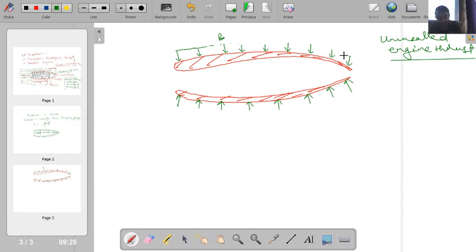Okay. Now I can consider that this is my body. So this is, say, the outer control volume of the fluid which is applying pressure P infinity over here. Now inside also some pressure will be acting because of the inside gas. So initially the gas will have pressure close to free stream. Then because of the compression process, this pressure will keep on increasing. So you see, I am actually increasing the size of the arrow over here. Okay, so this pressure is increasing.